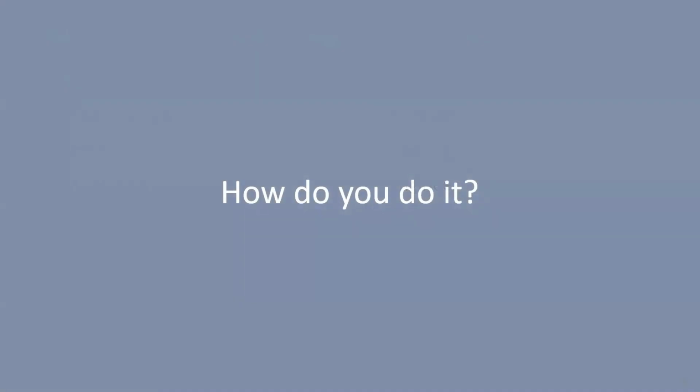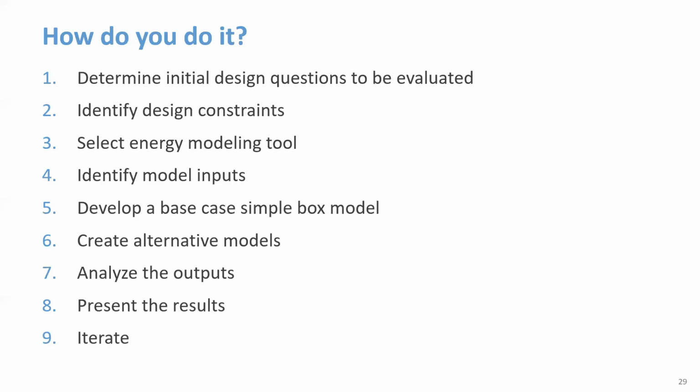So simple box modeling, how do you do it? There's no one right way to perform a simple box model analysis, but here's one perspective. Ideally, start by determining the initial design questions to be evaluated, then identify any specific design constraints, select an energy modeling tool, then identify appropriate model inputs, then develop a base case model, follow that by creating some alternative models, analyze the outputs, present the results, and then iterate or do it all again.